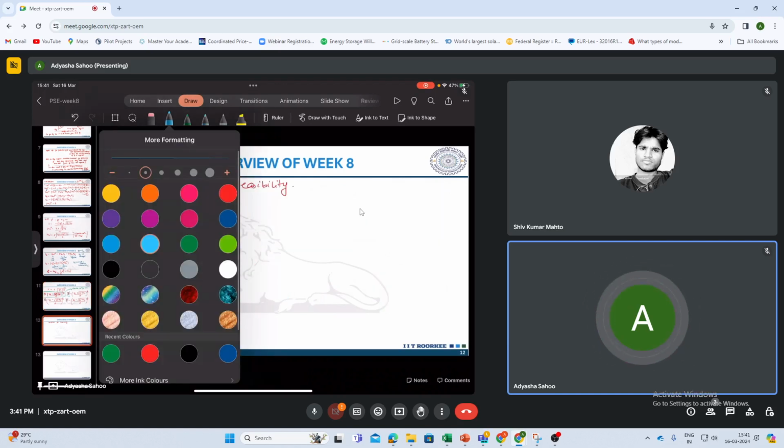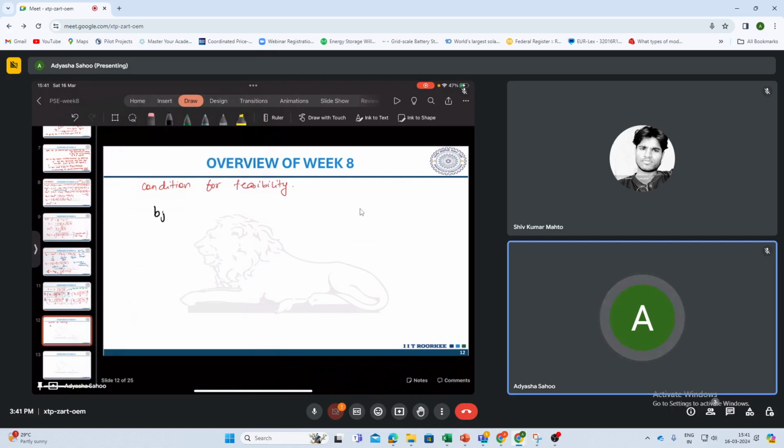So for satisfying that, we write BJJ square minus 4CJJ has to be positive or non-negative. So let us expand that. BJJ was Vm1 square minus 2Pm2 RJJ minus 2Qm2 XJJ, whole square. So that is greater than or equal to 4 times CJJ, which was RJJ square plus XJJ square, into Pm2 square plus Qm2 square.